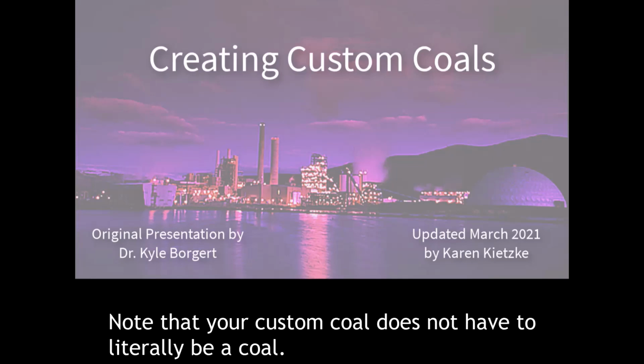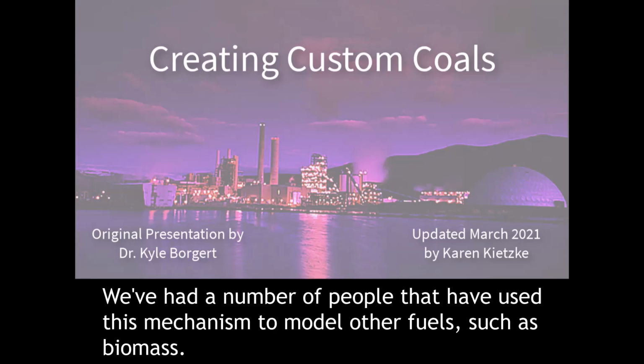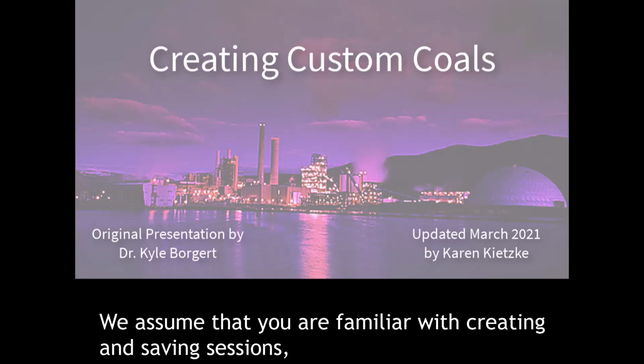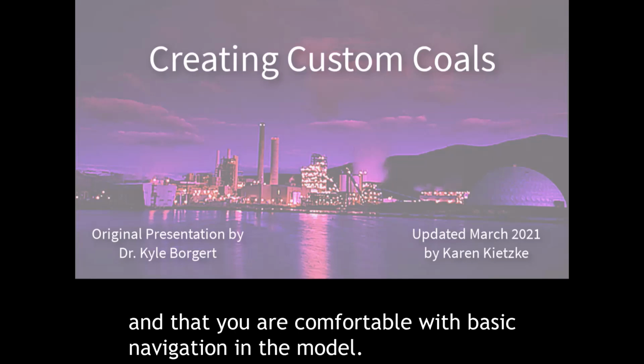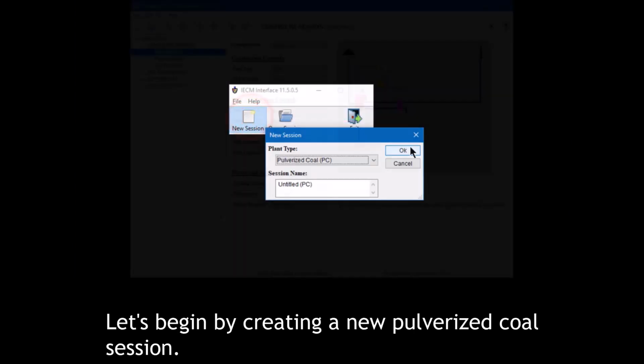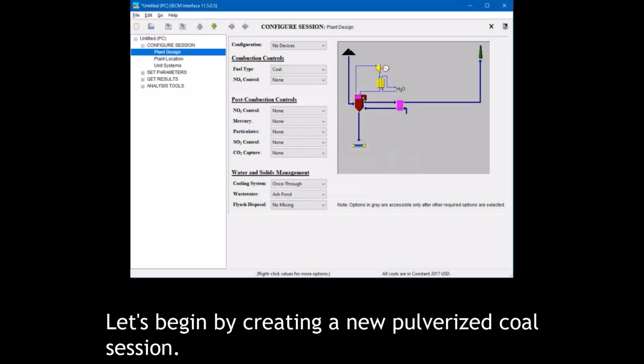This video will show you how to create and use custom coals. Note that your custom coal does not have to literally be a coal. We've had a number of people that have used this mechanism to model other fuels such as biomass. We assume that you are familiar with creating and saving sessions, and that you are comfortable with basic navigation in the model. Let's begin by creating a new pulverized coal session.